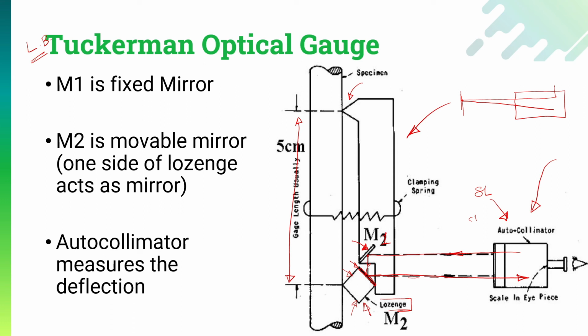Basically, these optical gauges are capable of measuring both static and dynamic strain, because they give us the value directly without any kind of inertia. So we will be able to see the real time changes in the strain directly.